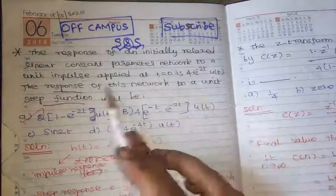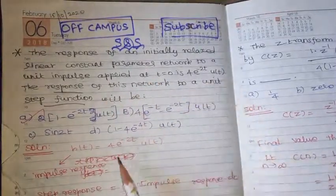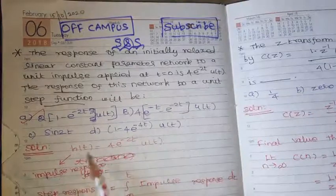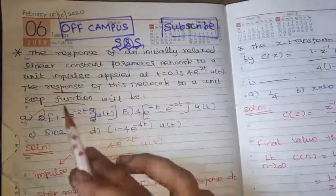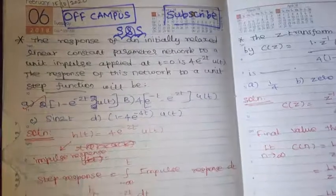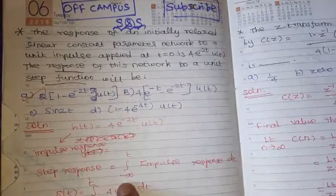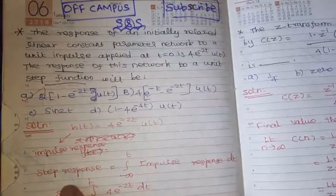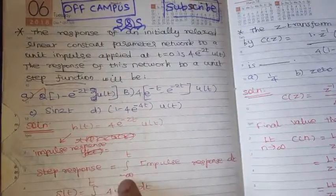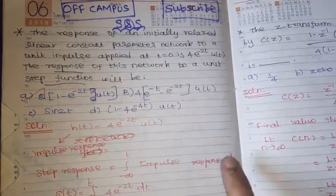So what is this impulse response? h of t equal to 4 e power minus 2t into u of t. This is the impulse response, and we need to find out the step response. How can we find the step response from impulse response? The general formula: step response equals the integral from minus infinity to t of the impulse response with respect to time.